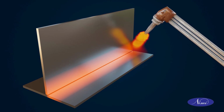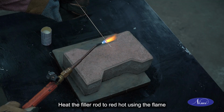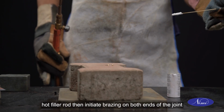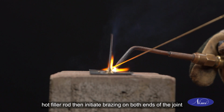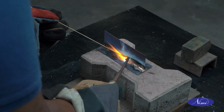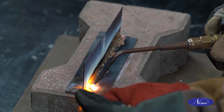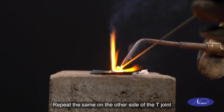Heat the filler rod to red hot using the flame. Apply flux in powder form by dipping hot filler rod. Then initiate brazing on both ends of the joint. Select the brass filler rod of 1.6 mm diameter. Deposit the filler metal along the entire length to complete the joint on one side. Repeat the same on the other side of the T-joint.